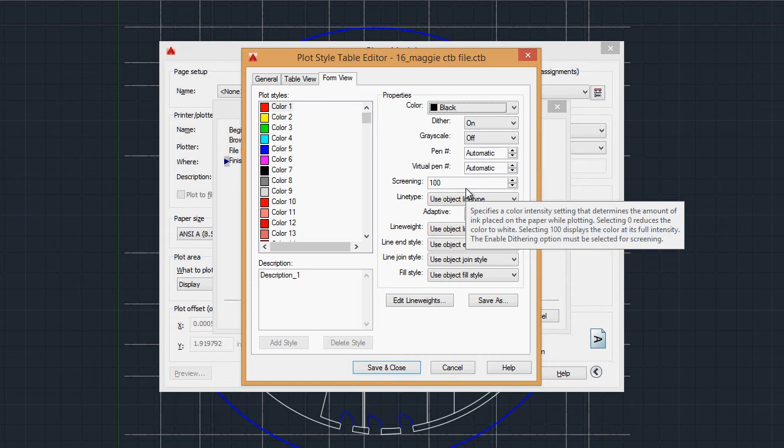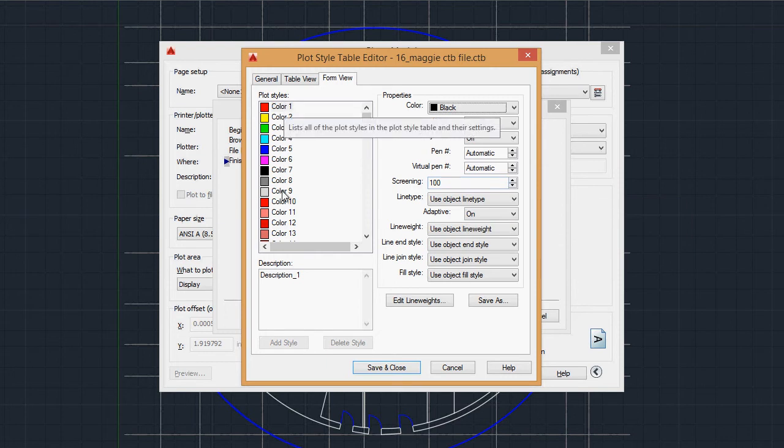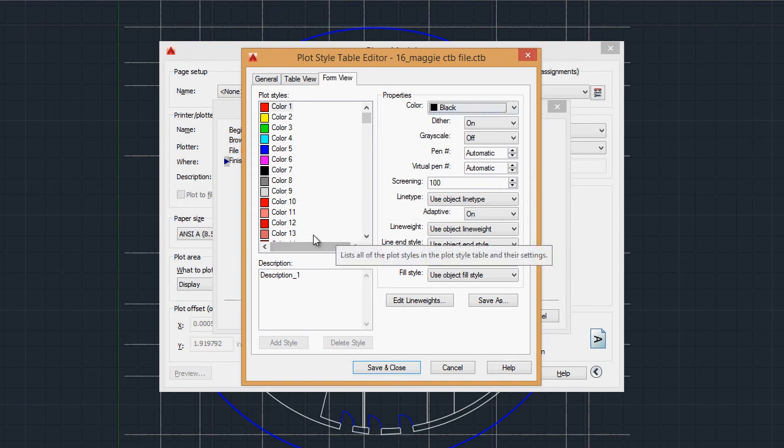So it's helpful to remember, if you want color in your AutoCAD drawing, just assign a color to a layer that's not defined to plot with a black pen. As long as our first 9 are being used as line weights for real lines and real objects in our file, we're going to make all of these black. But if we want to add hatches with a color, then we would go to a layer color that we're not assigning a black pen to, and as long as we print out in color, that's going to print out in color.